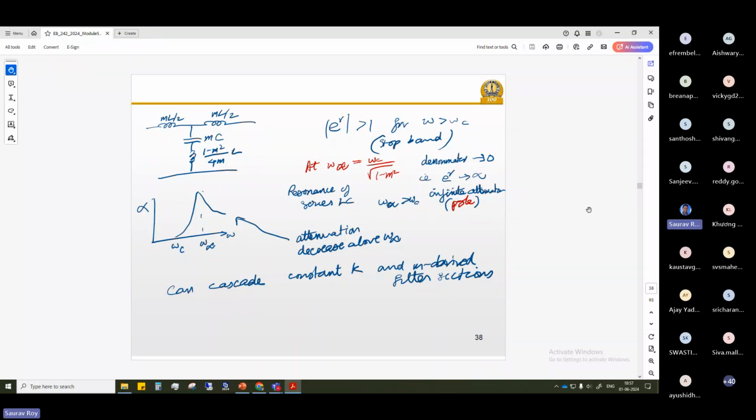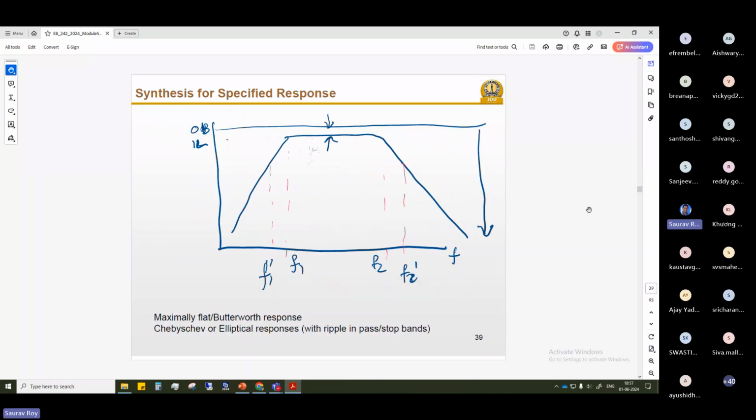So far, this is the basic analysis of a filter. But now, as you know, everything cannot be calculated using basic math. You can have an intuition from this, and that is how you have to go forward. Then how do you calculate? Generally we use a Butterworth filter, Chebyshev or elliptical filter. How do we do that? If we need a filter, generally it is specified in terms of insertion loss or return loss. So how do we link that to the theory?